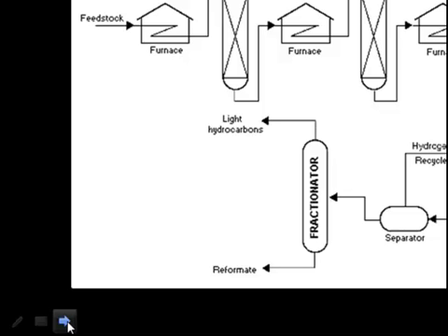In the reactor, the catalytic reforming takes place, where the product will be reformed into different products. So it may be a multiple stage reforming section, where we can use a combination of one or more techniques. Then the separator will separate the reformed product and the unreformed product, and the unused hydrogen we can have for recycling. Then the product will consist of many components which are formed during the reforming. So the fractionator will separate them into the reformate, which is reformed, and the light hydrocarbons.